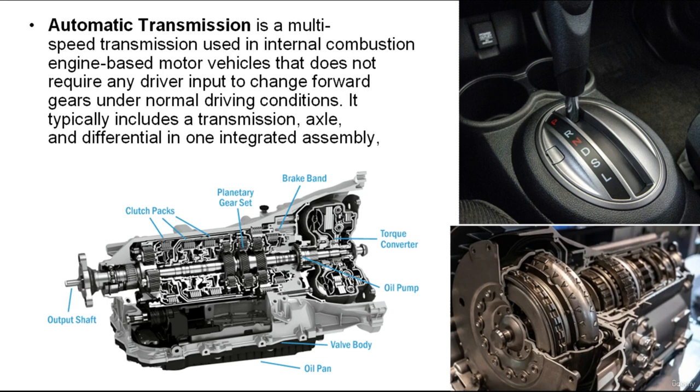In a hydraulic system, a network of valves and other components use hydraulic pressure to control the operation of planetary gear sets. These gear sets provide the 3 or 4 forward speeds, neutral, park, and reverse gears normally found in an automatic transmission. Newer electronic shifting systems use electric solenoids to control shifting mechanisms. Electronic shifting is precise and can be varied to suit certain operating conditions. All automatic transmission-equipped vehicles with OBD2 have electronic shifting.